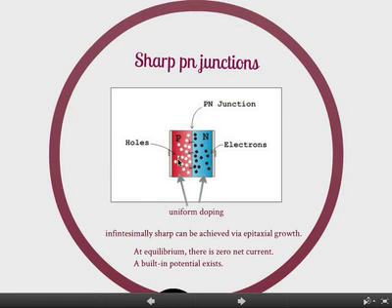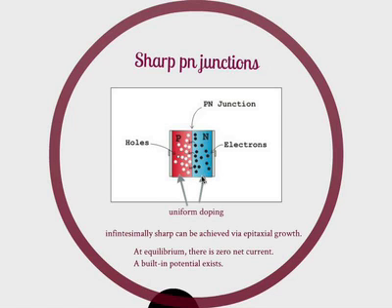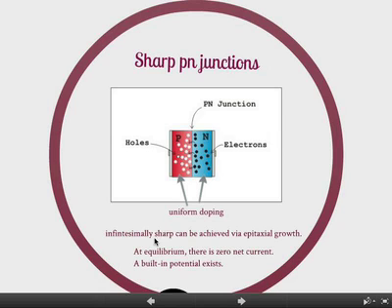So essentially, you have P-type, you have lots of holes here. N-type, you have lots of electrons here. And we assume it's uniform doping. So you have uniformly doped regions, except right at the boundary where you have the sharp change, right? So obviously, that's not uniform. But away from the boundary, it's all uniform doping. Okay? So the basic assumptions are your infinitesimally sharp boundary.